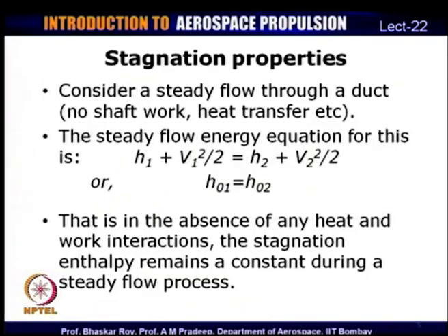This means that in the absence of any heat and work interactions, the stagnation enthalpy remains constant during a steady flow process. This is a very significant property that we need to keep in mind: if there are no heat interactions or work interactions in a steady flow process, then the stagnation enthalpy of such a process remains the same. It does not change if there are no heat transfers into or from the system.